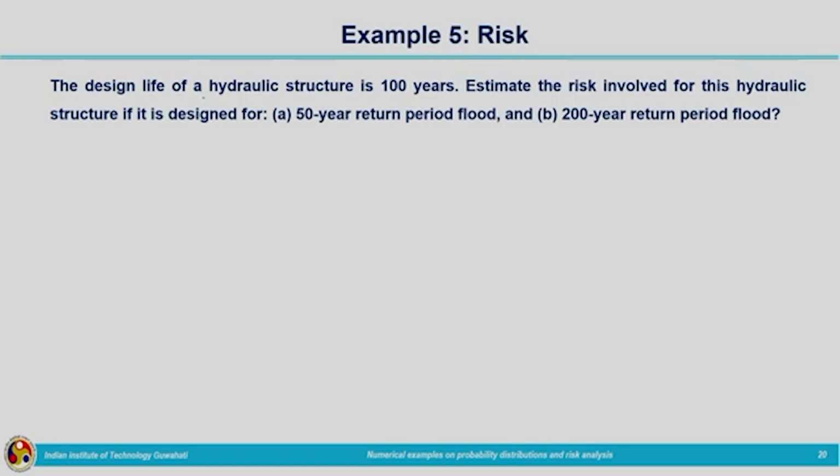Now let us move on to solve some examples related to risk. Let me first read out the question. The design life of a hydraulic structure is 100 years. Estimate the risk involved for this hydraulic structure if it is designed for a 50-year return period flood and a 200-year return period flood. Two cases are there. The design life of the structure is 100 years, and we need to compute the risk in two cases. One for the case of a 50-year return period flood, and the second one for the case of a 200-year return period flood.